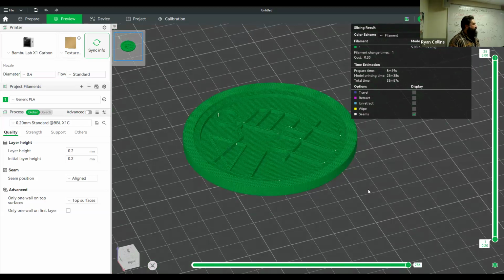I have something slightly more complex. 30 hours? What the hell? That's not wildly uncommon. Because sometimes it's not necessarily that you're going to be using up 30 hours worth of material. It just can take that long to deposit the material down. Sometimes we have to use what's called supports because it's an object that can't physically exist as it would be because gravity exists, or it might tip over or something like that. You need to create supports.